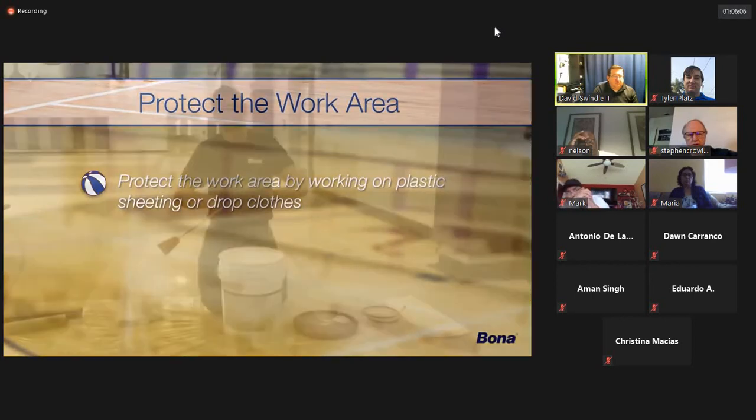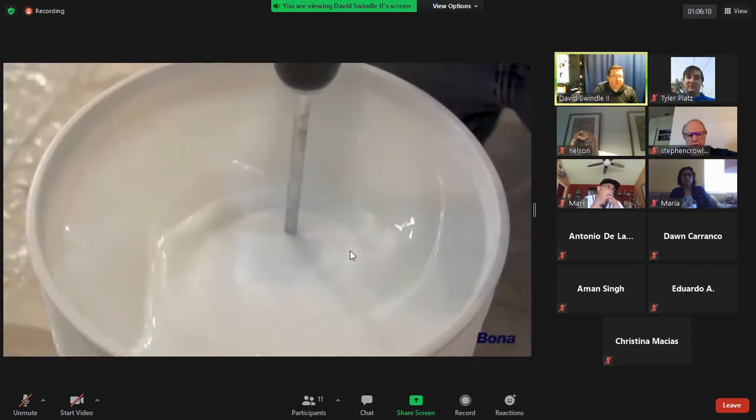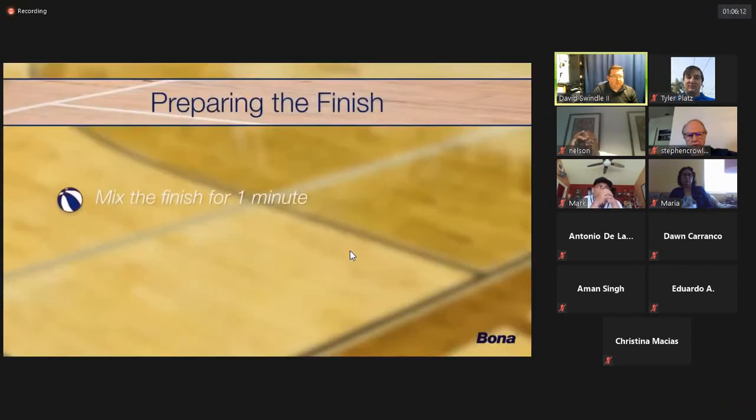Remove the lid from the bucket and insert the paddle mixer into the finish until it reaches the bottom. Mix the finish carefully and thoroughly for 1 minute. Allow the finish to rest for 5 minutes before use. If you don't have a drill...